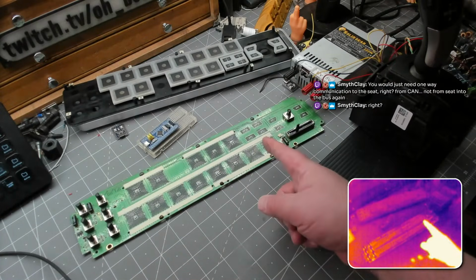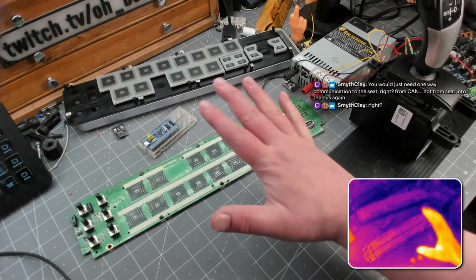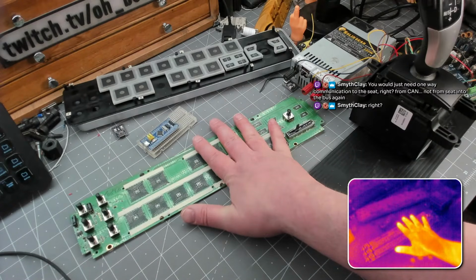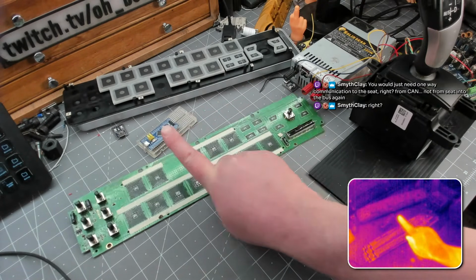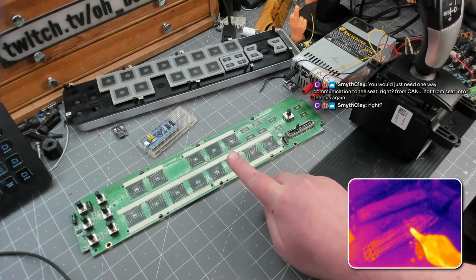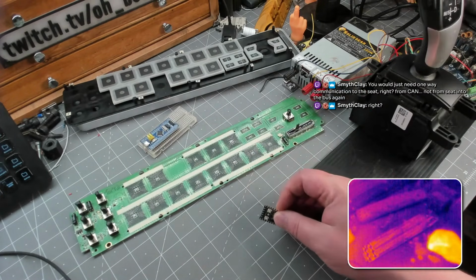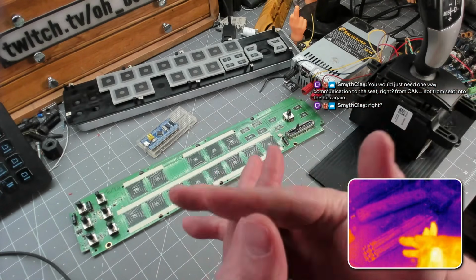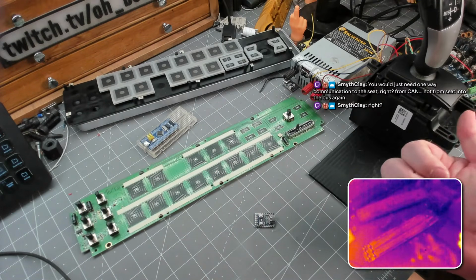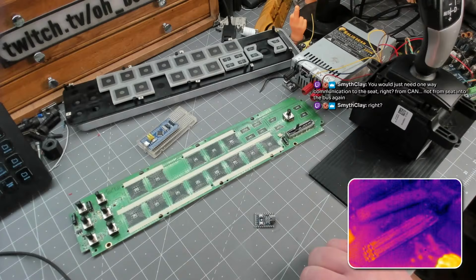So I looked it up, and it turns out that we can load an Arduino-compatible bootloader into the STM32, which means we might be able to get this thing hacked pretty quick. And if I can turn this program into a shell of a CAN bus communicating button thing, I can translate that over to some RP2040s, and we can take over more of my peripherals. So we can get a nice busy CAN bus going so that I can install Node-RED onto the Raspberry Pi and see if that will work properly.